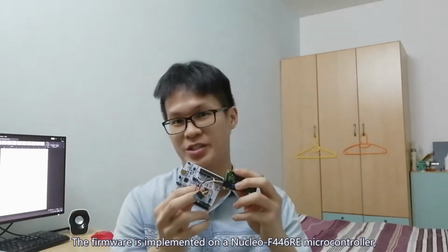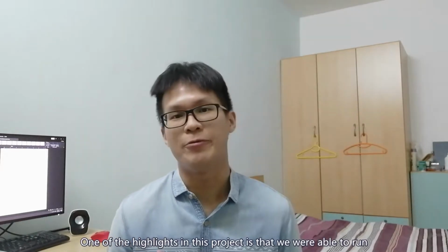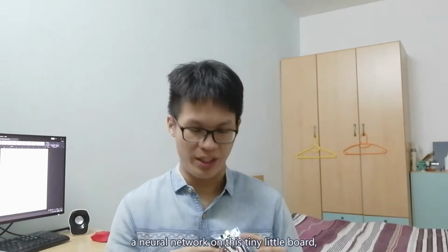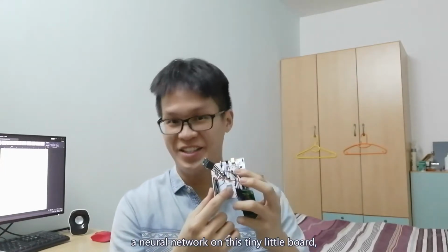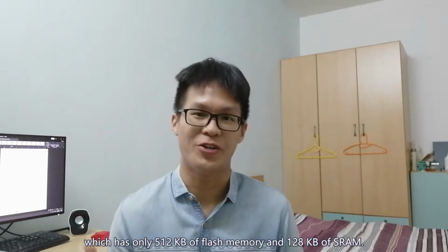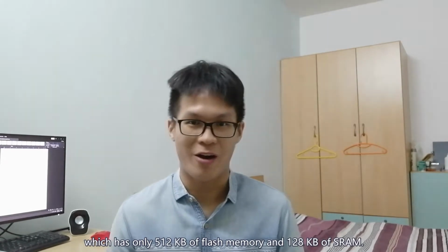The firmware is implemented on an STM32 Nucleo F446RE microcontroller manufactured by ST Microelectronics. One of the highlights in this project is that we were able to run a neural network on this tiny little board, which has only 512 KB of flash memory and 128 KB of SRAM.